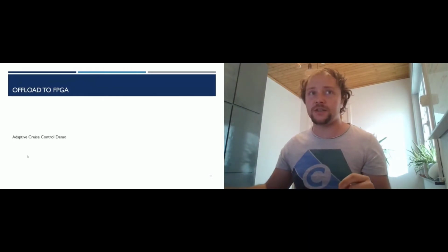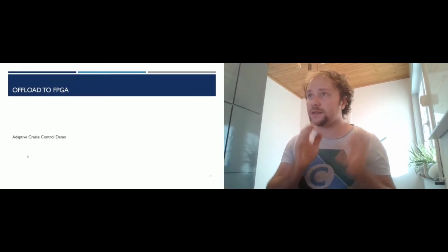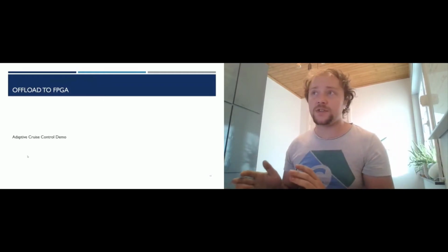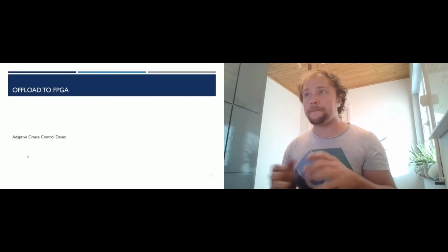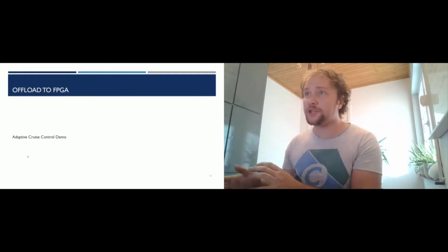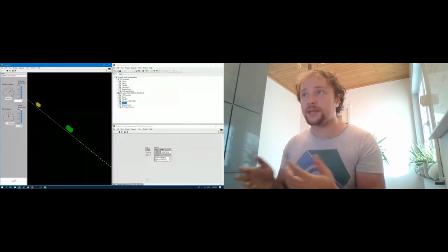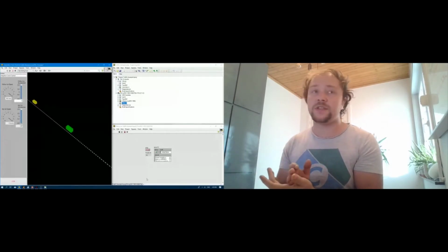So this interface is just an HMI. But all that was actually happening was the HMI was passing it on to the CPU. The CPU determined what it was supposed to do with it, either pass it on to the FPGA or handle it in another way. The FPGA looks at the data, in this case with a neural network that's on the FPGA, and passes this back to the CPU.